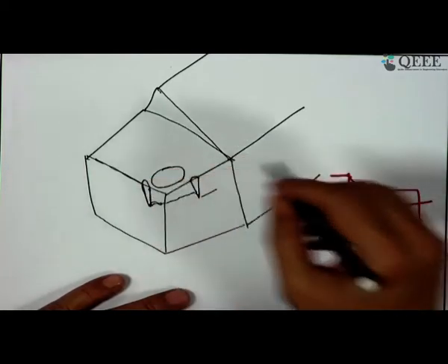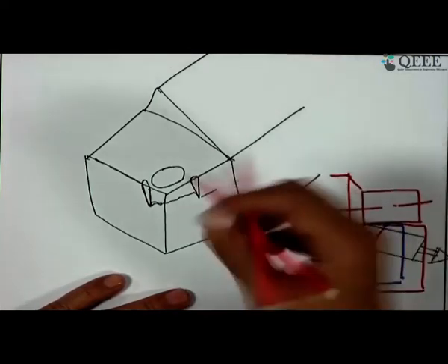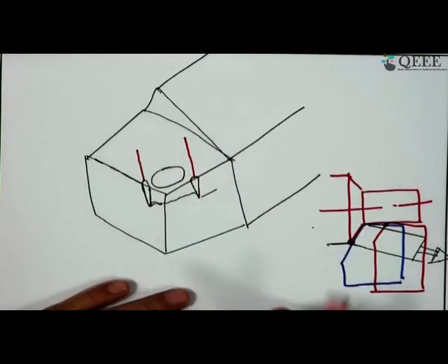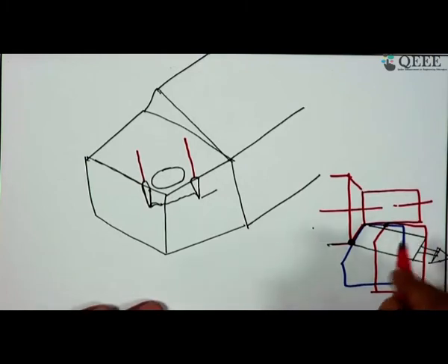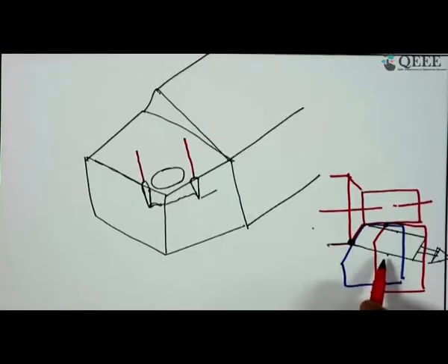So, the chip is sliding. There is a sliding mark, that means as the chip flows, the chip is following these two lines. So, two edges of the chip, please look at what I am trying to locate: this is one edge of the chip, and that is another edge of the chip. These two edges can be characterized by three qualification adjectives: they are hard, they are hot and they are sharp. They are also acting like two knives.